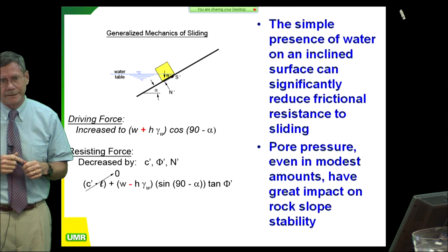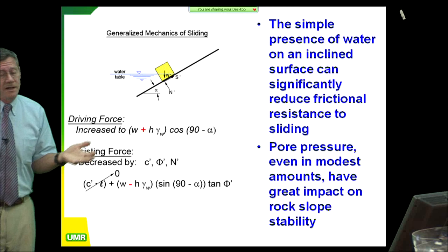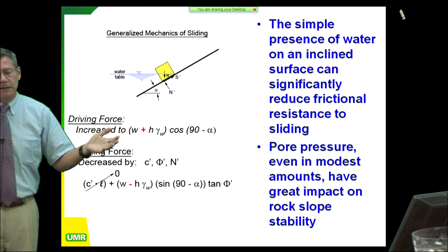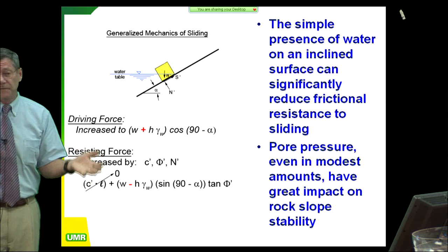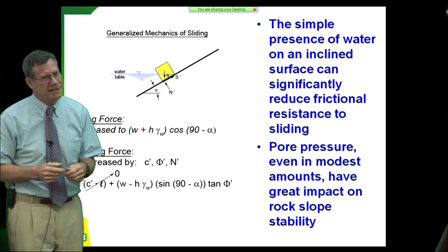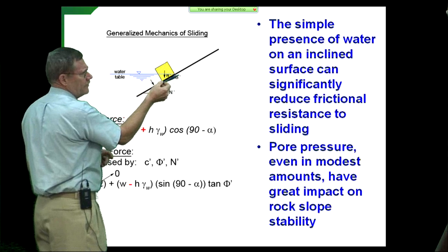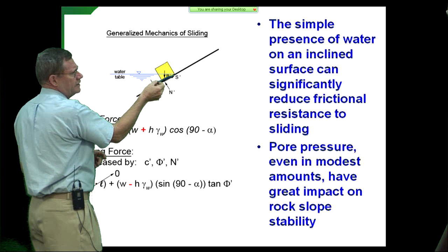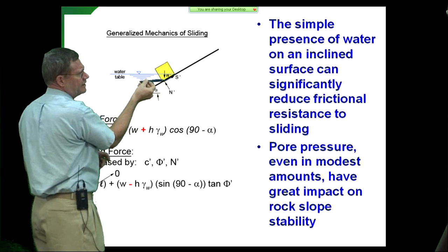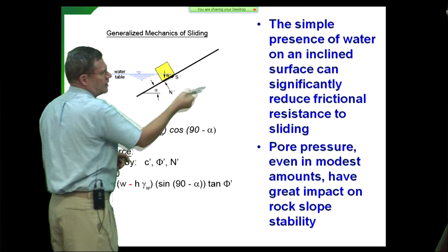Failed catastrophically. And they knew at the time that this is not a good thing, but they couldn't control it. They shouldn't have allowed that lake to fill until they could control something like that. That's the bottom line of that. And that was one of the lessons out of Teton. But what you have here, if you have a pore pressure imbalance, you have big trouble. So you can actually let the lake fill up, and it fills fast. That's not going to cause landslides.